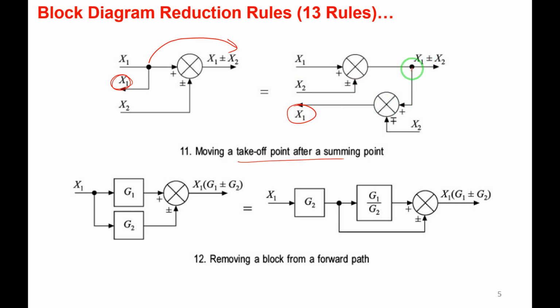Just let me check it, right? Here the input signal x1 plus or minus x2 is coming, but I want only x1. So subtract the other signal. So minus plus x2 you add, so that I will be getting x1. Means if I apply any rules, the functionality should not change, right? The signal should not be affected. I should apply the rules in such a way, right? Okay. Totally 11 rules are covered now.